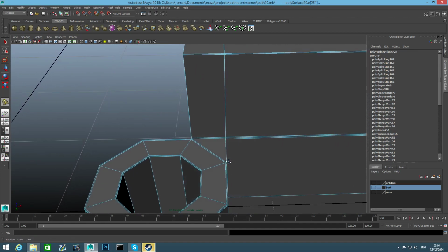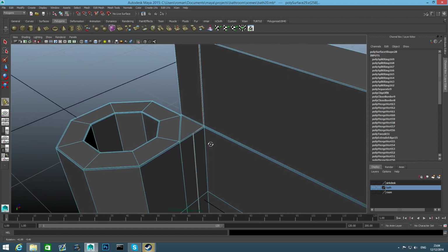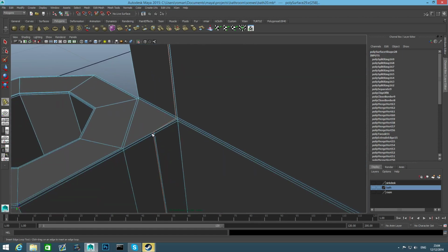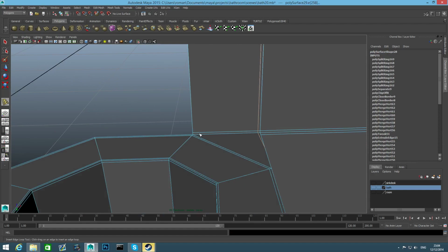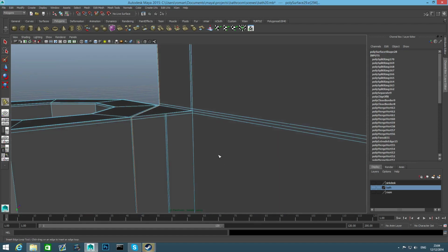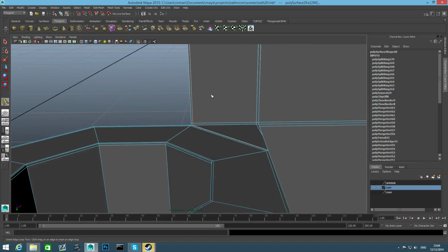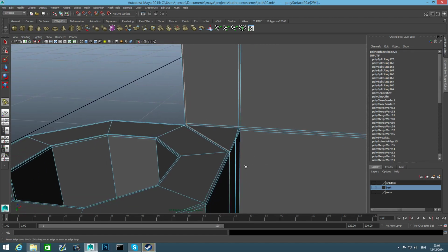So now I will be able to grab and enter here a whole full loop of edge loop. See? Just passing the same point here. Then I will be able to add one edge loop over here. Without that one, it will simply create only a line here that will end up here, and just the second one will be a full loop like those two that I just added.